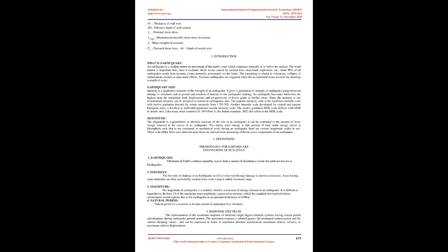2. Notation. Important letter symbols generally used are listed here for reference. Other symbols are covered in the concerned sections. Design horizontal seismic coefficient, Ah. Acceleration due to gravity, g. Height of structure, in meters, h. Importance factor, I. Number of stories, n. Lateral force due to earthquake or wind at floor i, Qi. Response reduction factor, R. Average response acceleration coefficient, Sa/g. Fundamental natural period, in seconds,